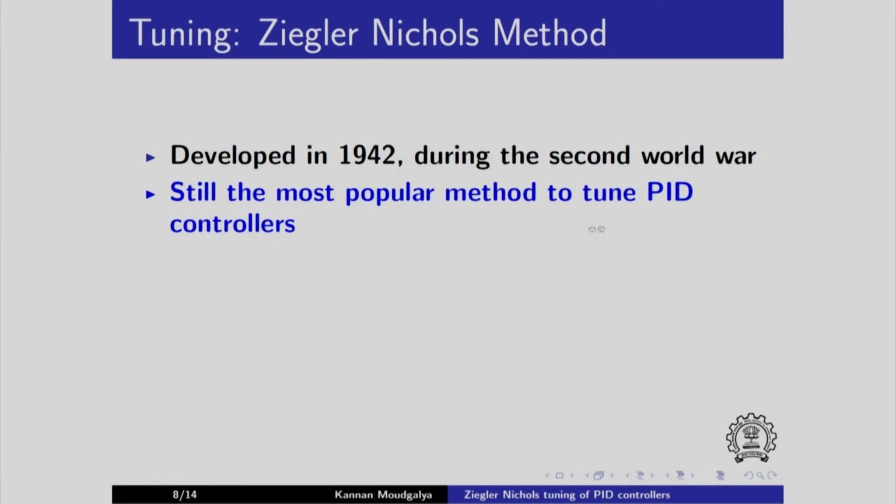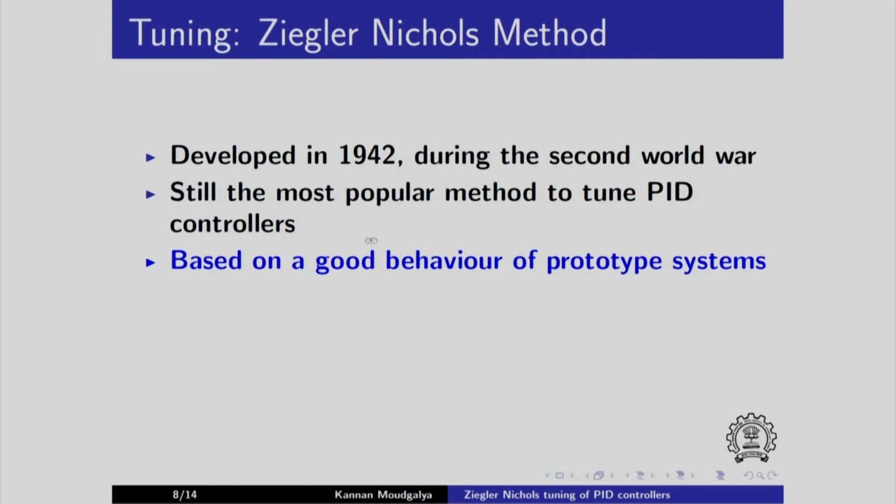It is still the most popular method to tune PID controllers. It is based on a good behavior of prototype systems. This behavior was defined by Ziegler and Nichols. Of course, further tuning is generally required because most systems are not necessarily similar to prototype systems.